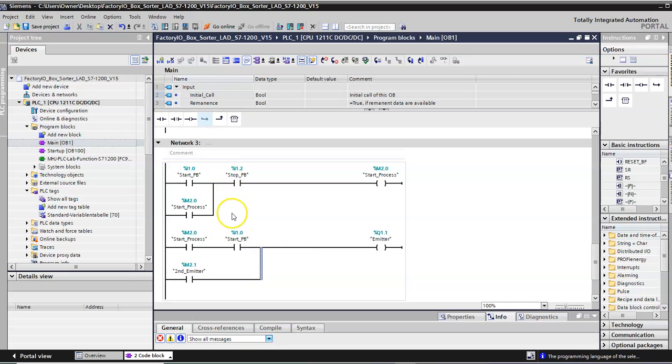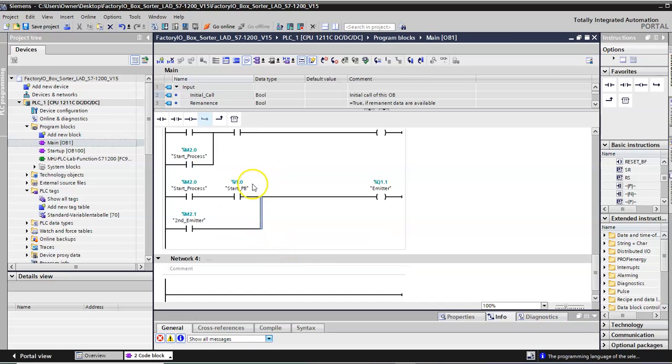You have to be a little more careful, for instance, if I went directly from start push button at 1.1 and I put in the stop, it's actually address 1.2. The PLC, from its own reasoning, if everything was wide open, would make it 1.1, and actually that 1.1 is the reset push button. So just understand that, and that's the reason that you should manually put in everything at the beginning.